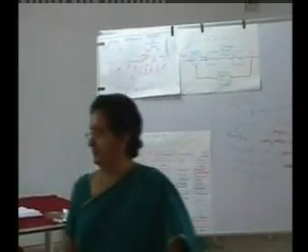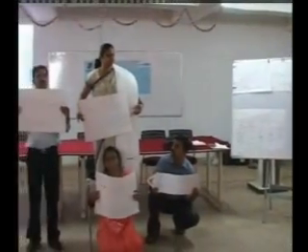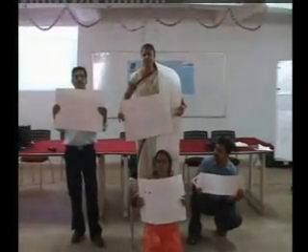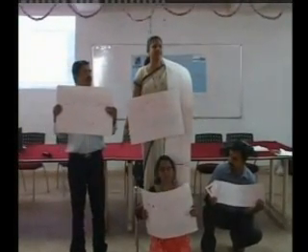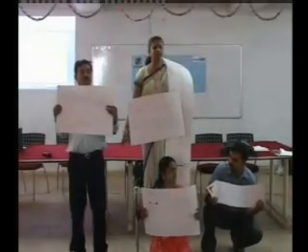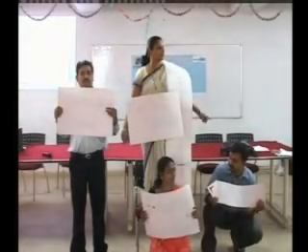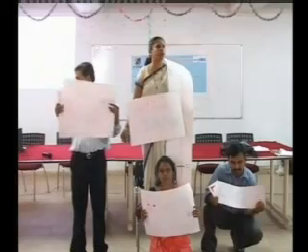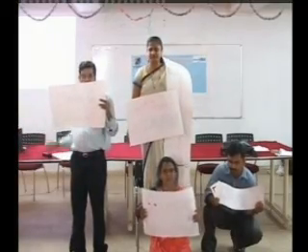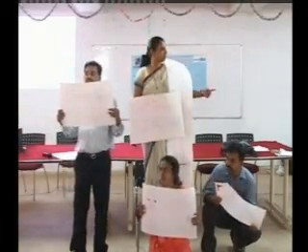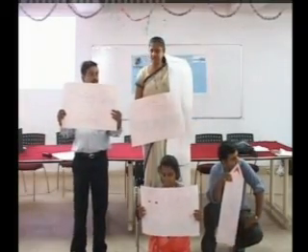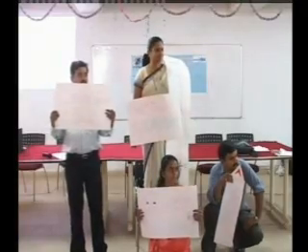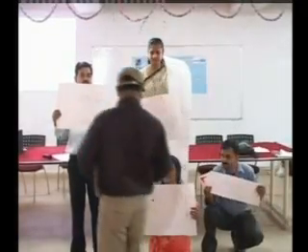I have become a smart tank because a probe, that is the sensor, has been introduced inside my tank, which will sense the level, both the lower limit as well as the upper limit, and accordingly the control action will be taken. I will be sensing the feedback signal, we take the error and give it to the controller. The controller will give an action on the final control element. The final control element will be the valve. Even now, the upper valve is closed, the lower valve is open, no water in the tank. So, the watchman comes and opens the upper valve.